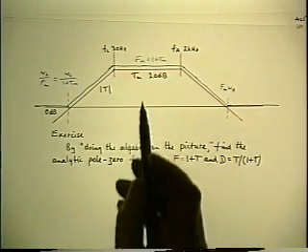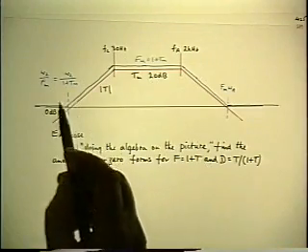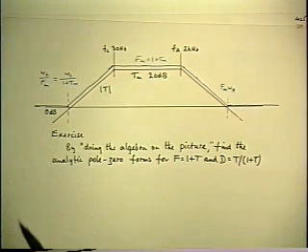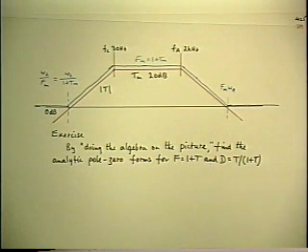So the only difference, because of the reverse frequency direction, is you divide omega 2 by Fm, and clearly from the geometry you have to divide it in order to get a frequency that's lower. And that's all there is to the construction. Now it's simply a matter of looking at the blue graph and writing the factored pole zero form.